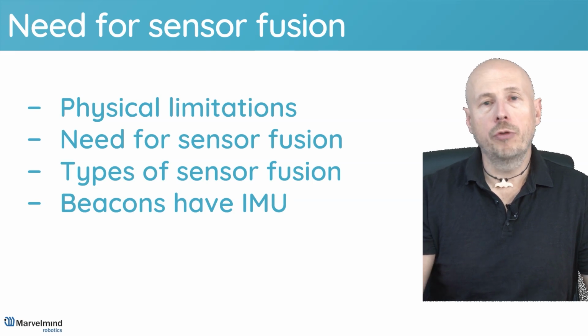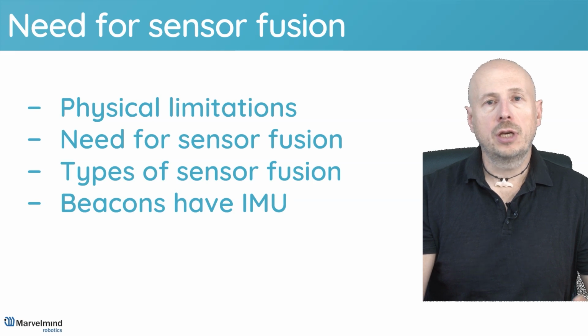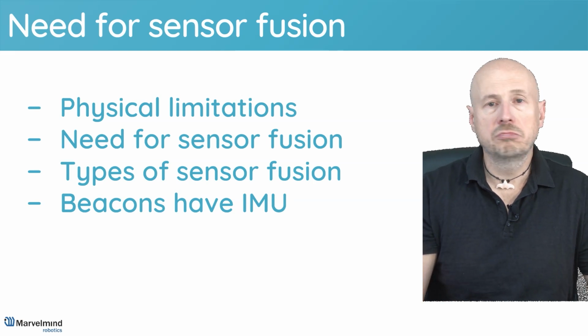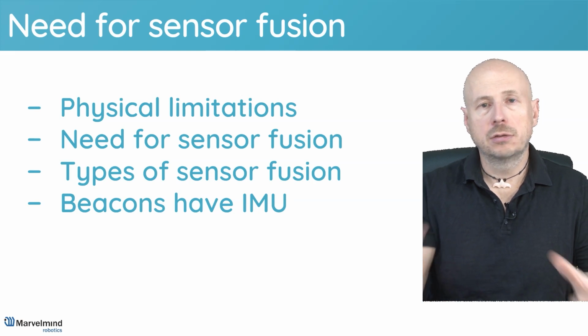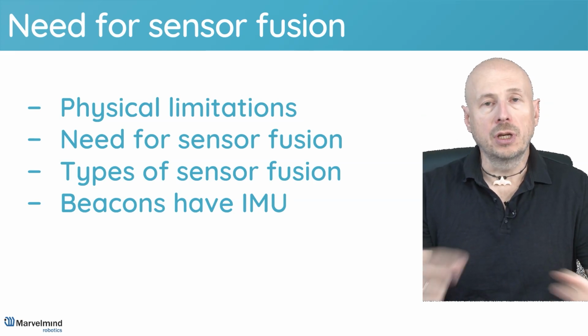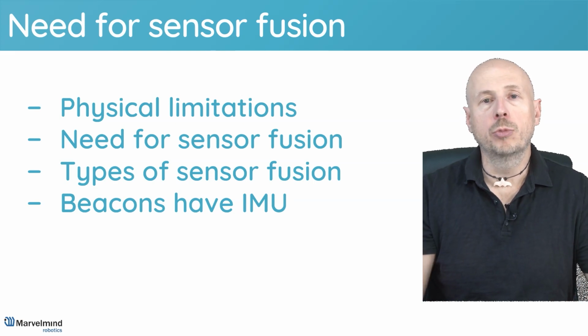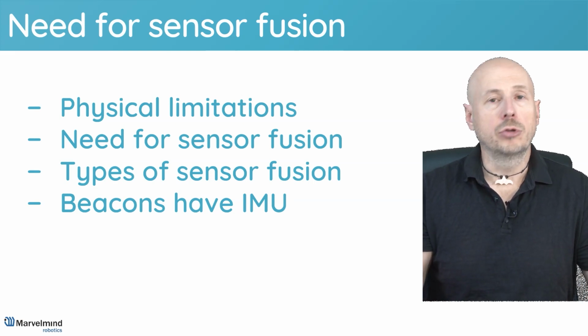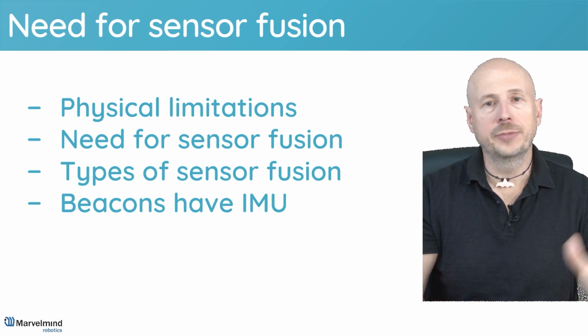Because none of them are perfect. Every positioning system can have some limitations. For example, optical: light, too dark, too bright, some obstructions. Odometry may slip and it may calculate that it's moving, but it's not moving. Ultrasound noise can block the system completely. In all cases, if radio is not available, you cannot get the data, you cannot update it, etc.